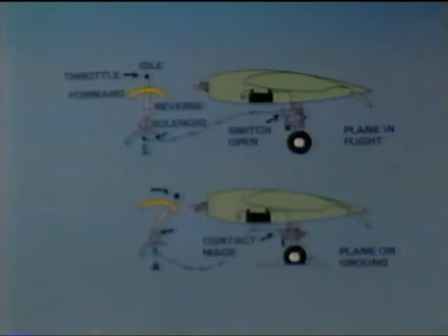Propellers cannot normally be reversed in flight, and the aircraft must often be below a specified speed on the landing roll before the props can be reversed. Many systems require that the aircraft be on the landing gear before the throttles can be moved into the reverse range. This is controlled by a squat switch on the landing gear strut.